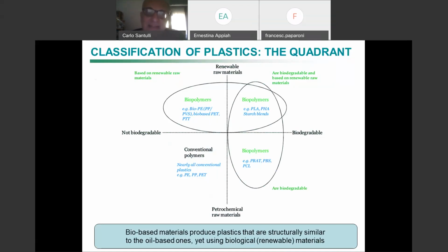This is a difference from metals. You may remember that there are molds also in metals, to produce cast iron pieces, so steel pieces, cast iron pieces, copper pieces, etc. But the disadvantage is that these molds can be used only one or a few times. Here, the molds can be used millions of times, so I can produce millions of PET bottles with the same mold, and the mold will not be damaged. So I can carry on using it.